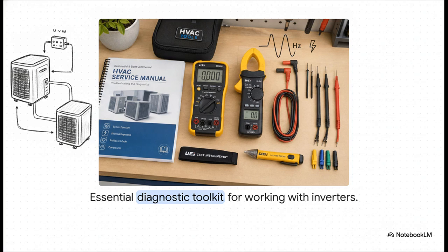And here's a pro tip. You need skinny back probe leads. I'm telling you, trying to jam a standard fat test probe into those incredibly tight UVW terminals is a guaranteed way to short out a very expensive board and ruin your whole day.